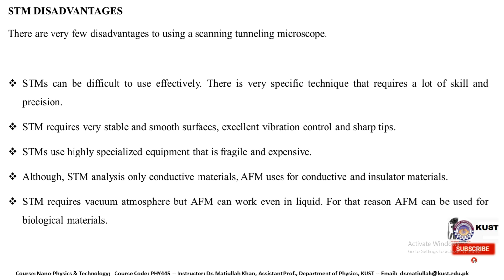STM analysis is only used for conducting material, as we discussed before. But AFM can also be used for non-conductive, insulating material. STM requires a vacuum atmosphere, whereas AFM can work even in liquid as well. For that reason AFM can be used for biological materials.